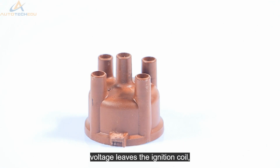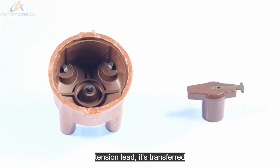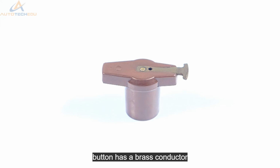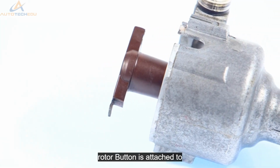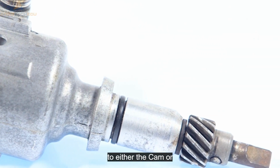After the secondary voltage leaves the ignition coil, it's delivered to the centre terminal of the distributor cap via a flexible high-tension lead. It's transferred through a spring-mounted carbon brush to the revolving rotor arm, or button. This button has a brass conductor along its surface. The rotor button is attached to one end of the distributor shaft, with the other geared to either the cam or crankshaft.